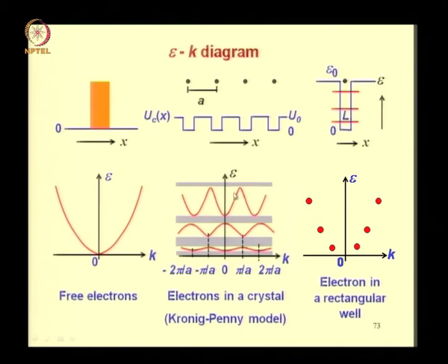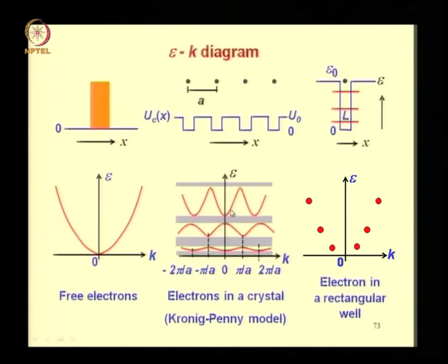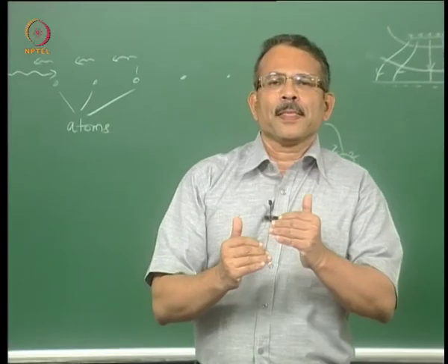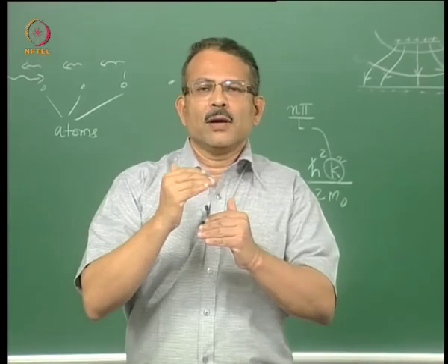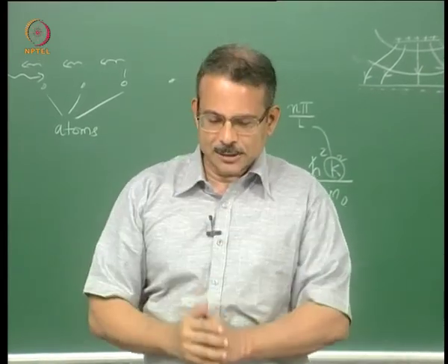So this entire band of energies is allowed, and within the band the behavior of energy versus momentum is periodic. So these are the features of this E-k diagram. E as a function of k is periodic. Then there are certain bands of energies which are not allowed and certain bands of energies which are allowed. So you have alternately located allowed and forbidden energy bands.